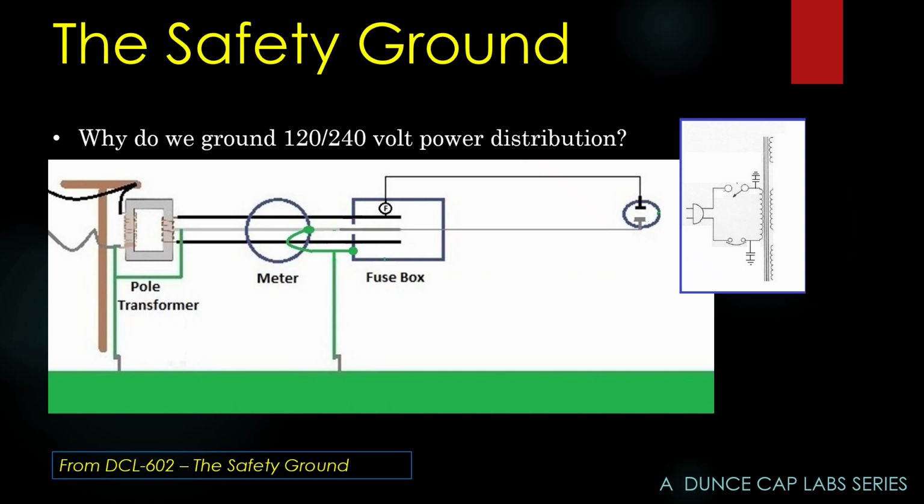This is a schematic of the input to the HW16. You might notice neither side is tied to ground in the cabinet. But what do you suppose is going to happen if this capacitor shorts? Now you've got the hot lead touching the cabinet. If I touch the cabinet and I'm also in contact with ground or a grounded object, I become part of the circuit and I'm electrocuted.